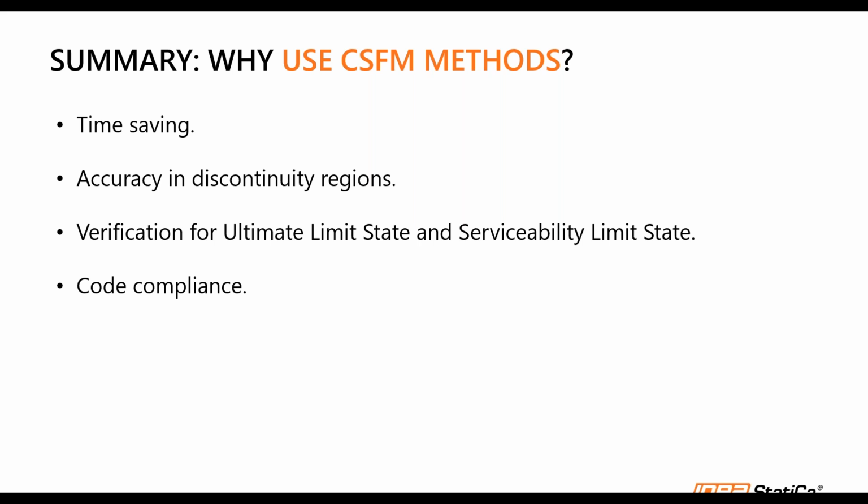Accuracy in discontinuity regions. With CSFM, it captures realistic compression and tension fields, while the strut and tie method is highly dependent on the engineer's judgment in choosing the truss model layout. Sometimes different engineers using different strut and tie models possibly have different layouts as well. And with CSFM, it covers verification not just for ultimate limit state, but also serviceability limit state. Lastly, code compliance: it supports various codes such as Eurocode, ACI code, and Australian codes.